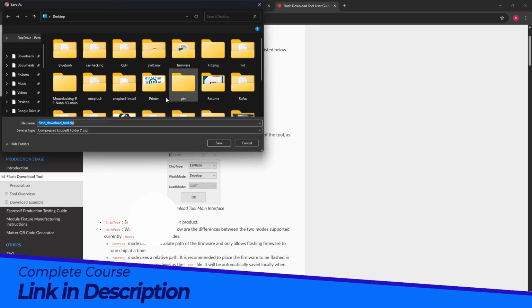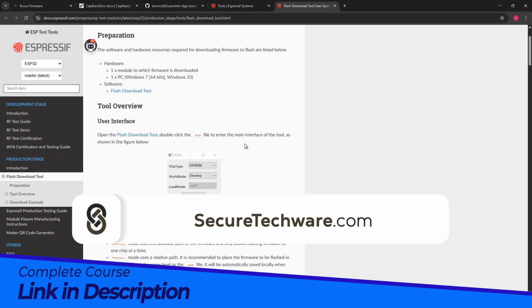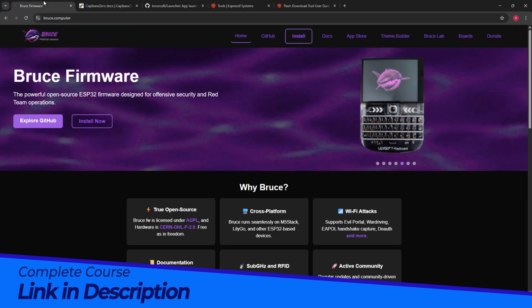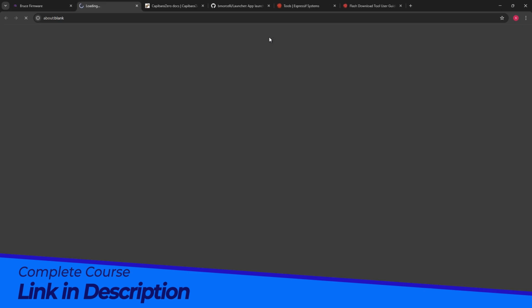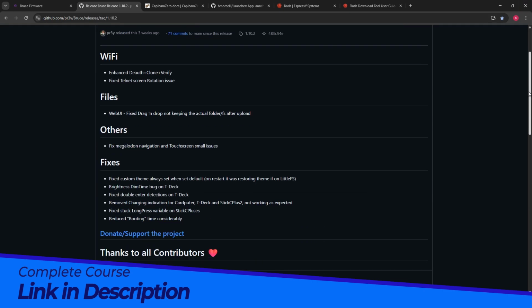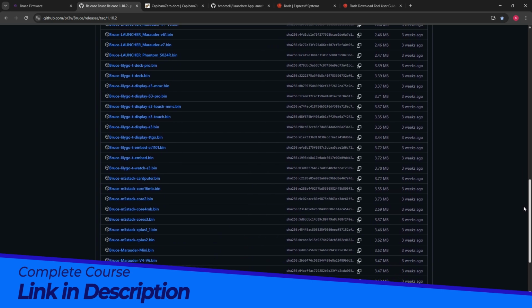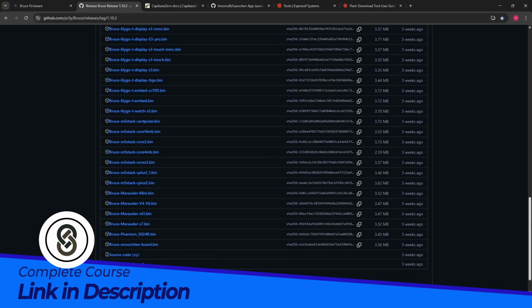I have already downloaded this tool, so you have to download this zip file and extract it. And then we need the bin files, the firmware files. You can go on any firmware site, like Bruce. You have to go to GitHub. Over here you can see Bruce releases, and over here you can see all the bin files. So we have to download the bin file for our CC1101 device, T-Embed CC1101.